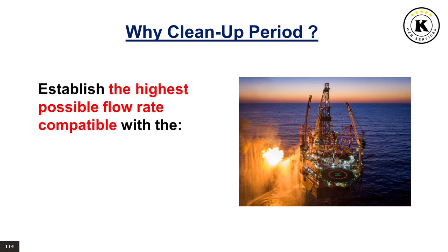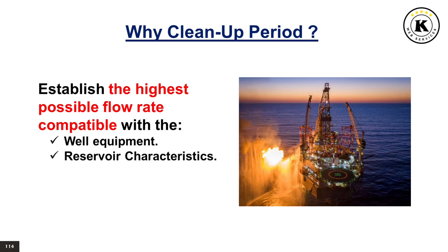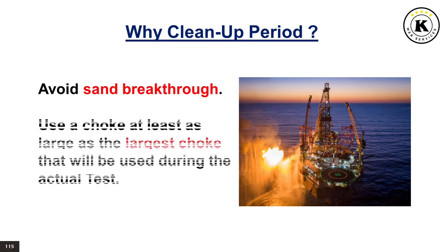To establish the highest possible flow rate compatible with the well equipment, reservoir characteristics, and surface equipment capabilities. To avoid sand breakthrough, and to use a choke at least as large as the largest choke that will be used during the actual test.